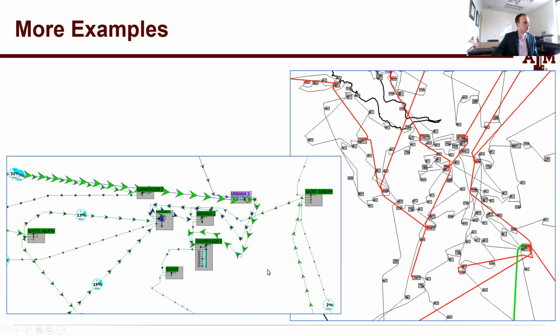There's a lot of applications for this kind of thing, which would be mainly if you have a power flow case that doesn't have a diagram, whether that's because the diagram you have is out of date, or you just got one from another system, or you don't have those diagrams, or in our case for synthetic grids, and you want to just get a quick look at it, try to get a good diagram that'll really show what's going on in the system. Here's one for that San Francisco Bay case I was looking at a minute ago, where you could see that these red 345 kV lines and the black, I guess this is probably 138 kV lines, have been routed around so that you don't have as many overlaps between the substations and lines themselves.